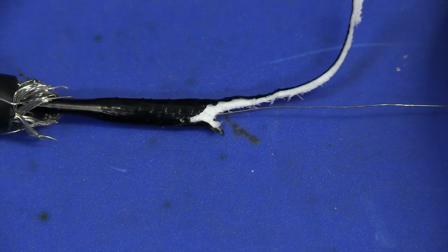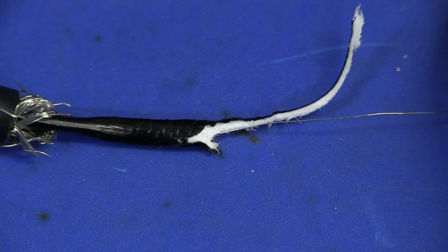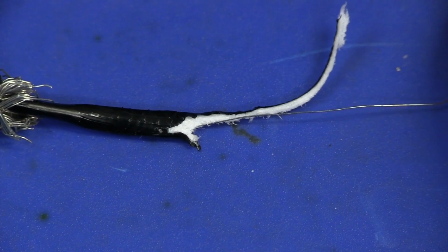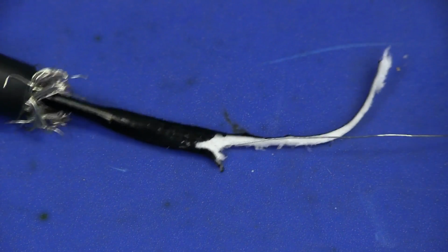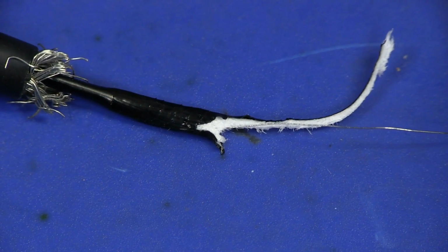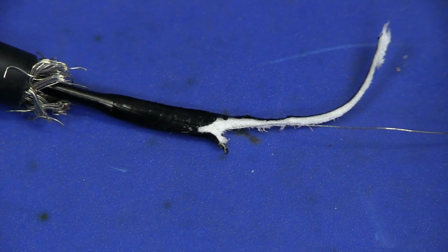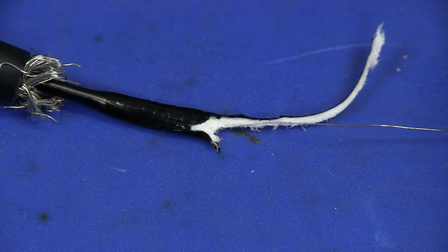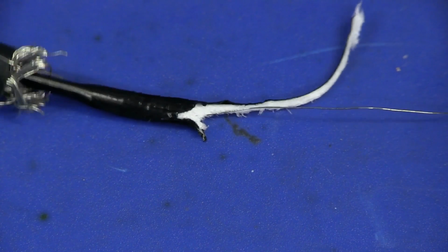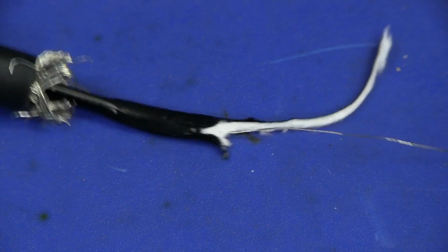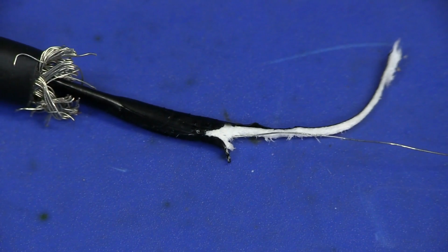So there's a lot of art and science which goes into the design of these probes, and then the matching compensation networks to give you a flat usable response up to, in some cases, well over 500 megahertz, which is really amazing technology. So these aren't just regular coaxes.